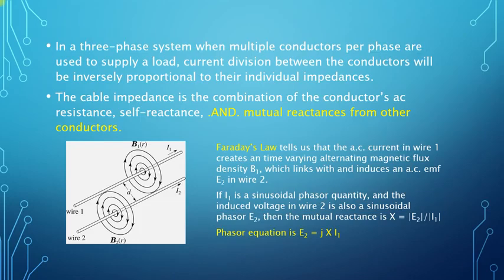The AC voltage drop in one cable conductor due to the AC current in a second cable conductor increases with the current in the second circuit. And this is basically a voltage induced by transformer action, i.e. it's an example of Faraday's law. The alternating current in the first conductor sets up an alternating magnetic field, and this alternating magnetic field induces a voltage in the second conductor.